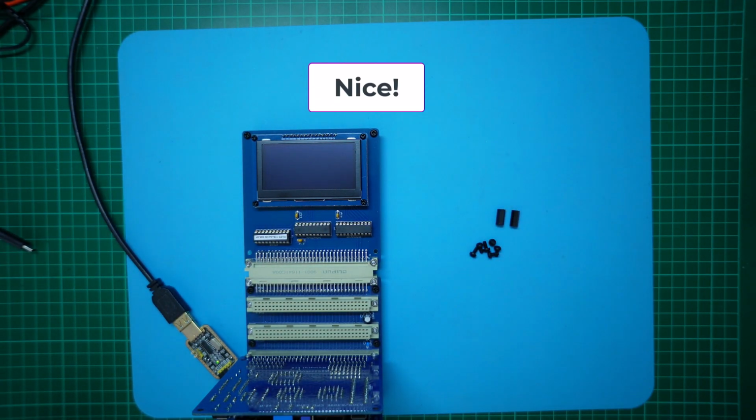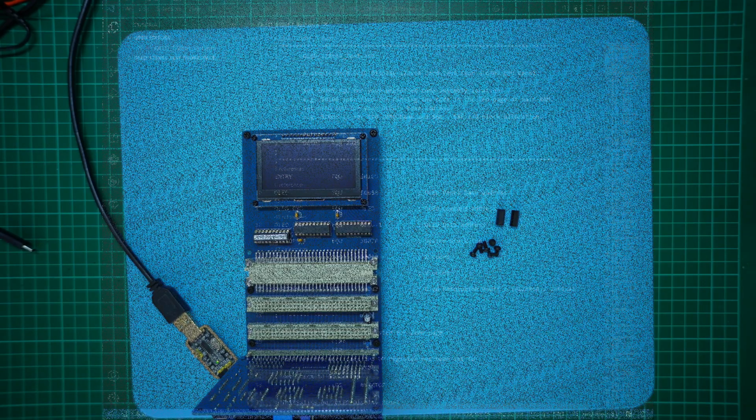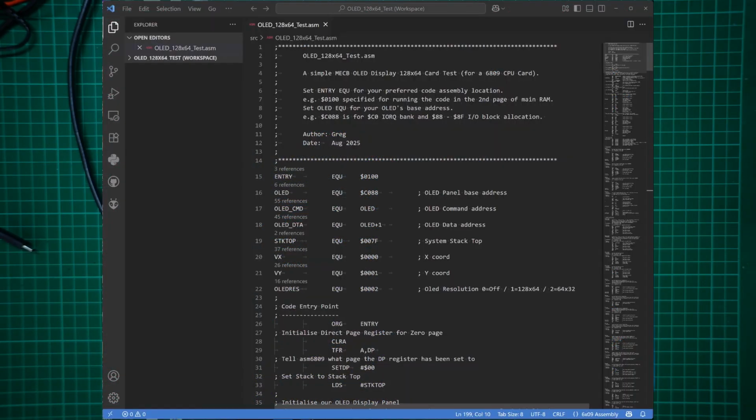Right, and we're ready. For the initial test, I've written some 6809 code to initialize the display panel and display some simple diagonal lines. All we need to know at this stage is that our display is working correctly and that we can control it with our retro 8-bit MECB system bus. So let's take a quick look at the code. Rightio, here you can see an OLED 128x64 test.